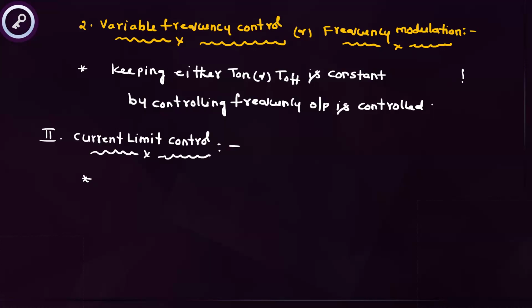See, we are varying the frequency now. For example, if you have to increase the output voltage, we have to increase the frequency. If you increase the frequency for a very large value, high frequencies may cause interference effects. That is one problem. A large filter is also required. Because of these drawbacks, it is not preferred.